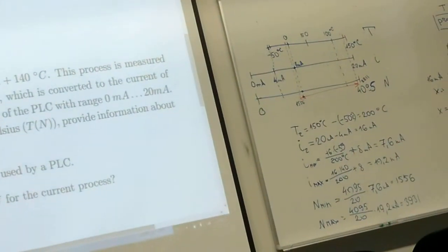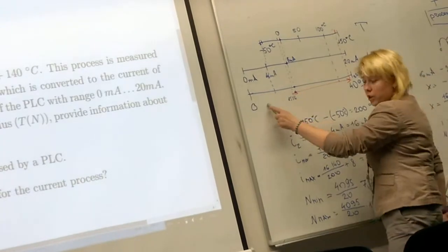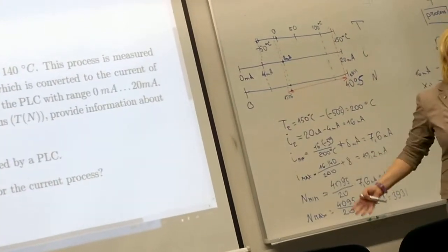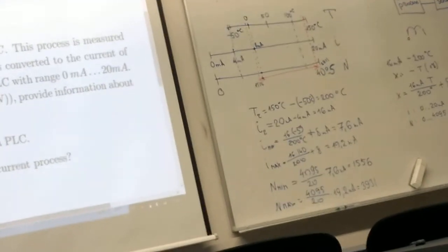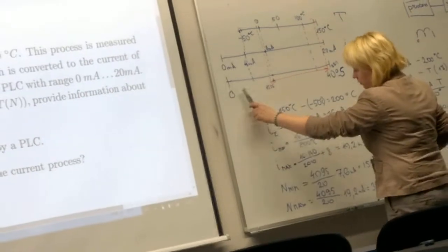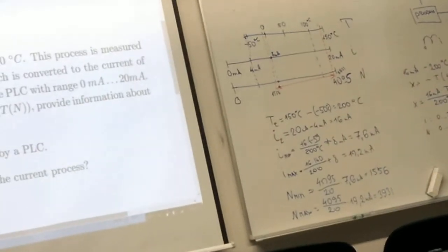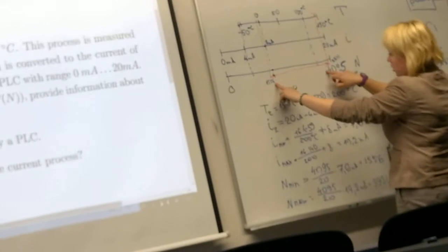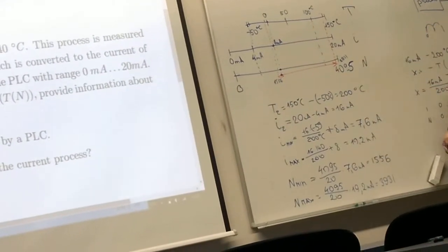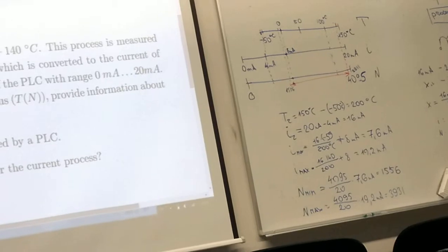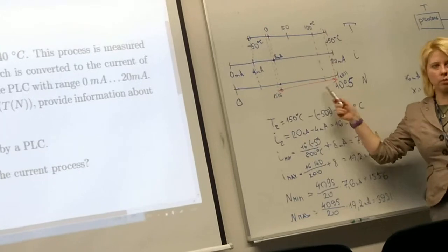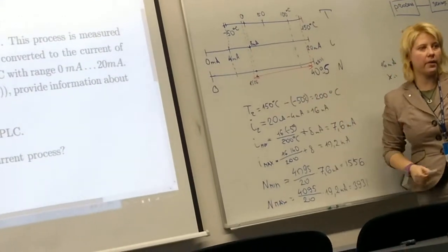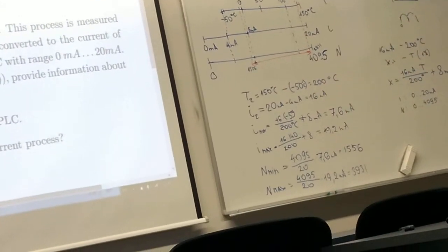When we tried to control it, we had problems because we tried in this range and nothing happened, so we couldn't understand what was going on. After that we found that physically our process is just in this range, so we could continue with control actions. So it's better always to check what values our PLC is dealing with.